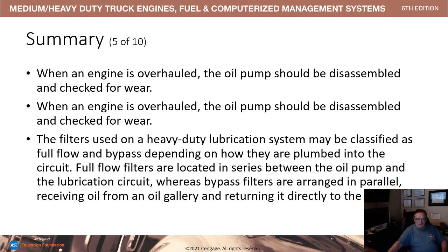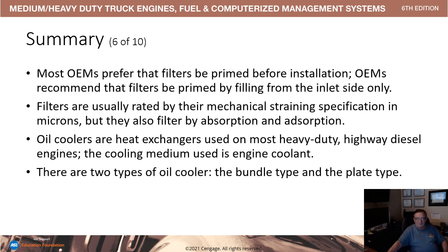Filters used on heavy-duty lubrication systems can be classified as full flow and bypass, depending upon how they're plumbed into the circuit. Most OEMs prefer filters to be primed before installation, filled from the inlet side only. Filters are usually rated by the mechanical straining specification in microns.